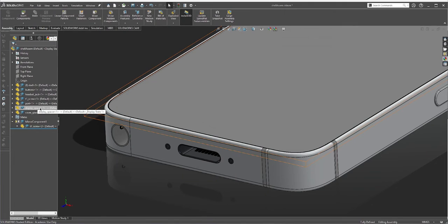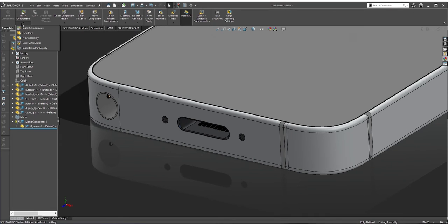If you can't use a pattern, at least reuse parts wherever you can. I have used a pattern for the second screw, but if I didn't and I wanted to add a second screw, I would still be best off inserting another instance of that same part file rather than modeling a second screw with all new geometry, even if it's identical. Cinema 4D is smart enough to recognize these patterns and reused part files, and it converts these to matrix instances which don't use anywhere near as much video memory in the Redshift engine.